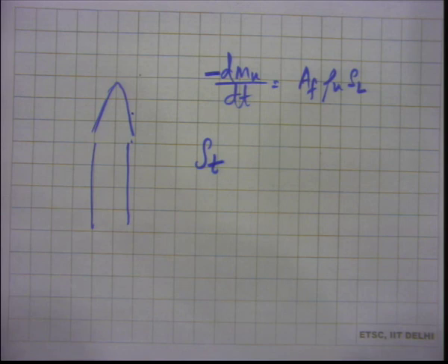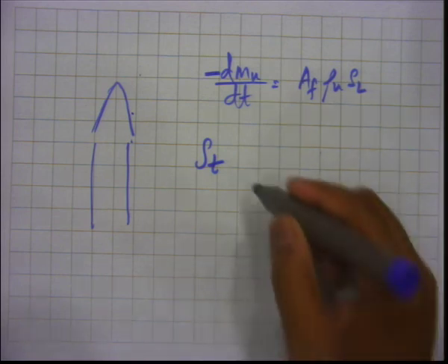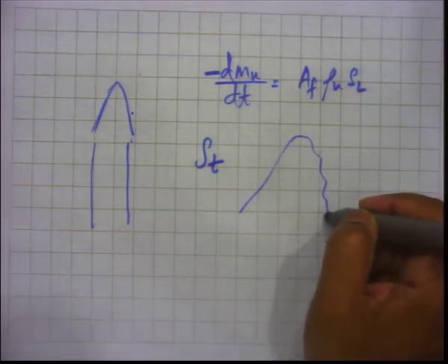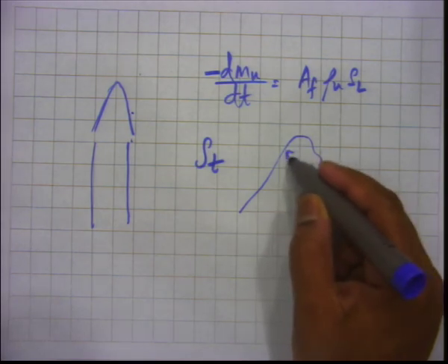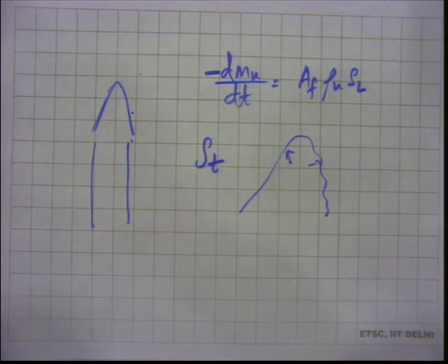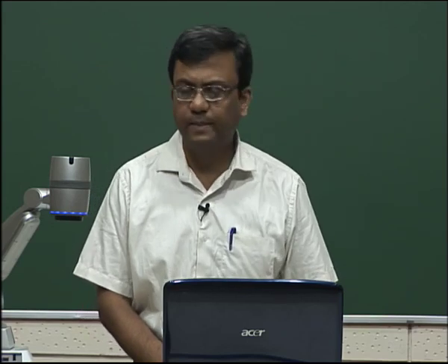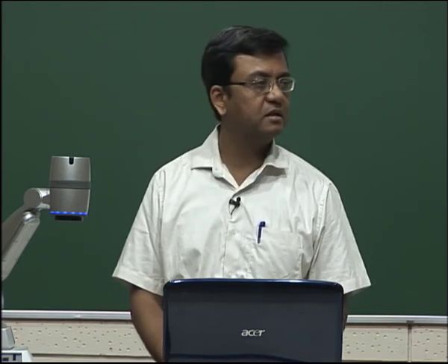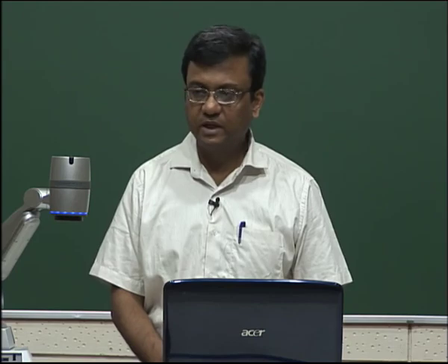but then measuring turbulent burning velocity is also very hard, because if the area itself is moving about, then getting the velocity with which the unburnt mixture is moving into that flame zone is very, very hard. Whereas for laminar burning velocity, even though we did not discuss this, I think you kind of know that it is not all that difficult to measure it. At least you can get an estimate quite easily in the lab.